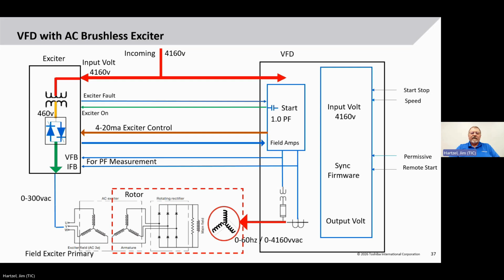So what this drive has an algorithm that will do is detect rotor position. The way we do that is turn on the field at first with a pulse on and then off. We're going to measure it. We're going to figure out what phase relationship we have, and then we'll output the proper phase relationship to the actual motor windings.